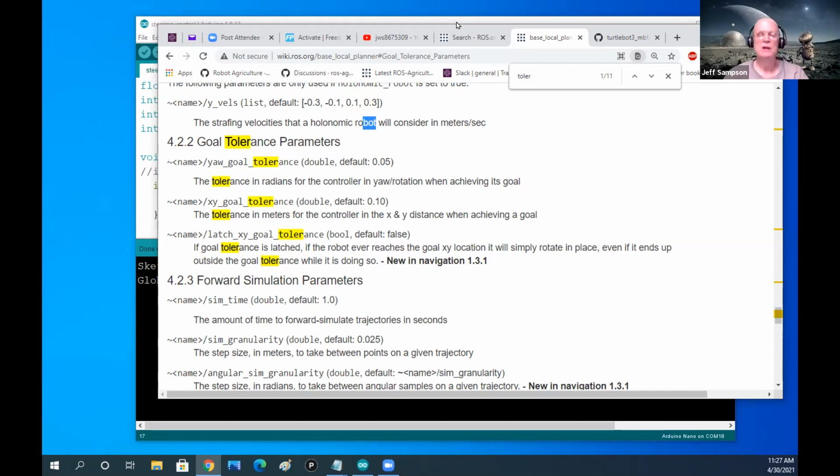So anyway, that's that. I posted the link to that file to give you an idea. Another thing you can do is when you first start up your software, at the very top, it lists a bunch of parameters that it's going to use, and see if it's got the goal tolerance stuff listed in that. Now, it could be that it only defines it if it's not set to a default. If you run your software on your lawn tractor and it lists all the parameters it's going to use, and it doesn't list goal tolerance, but if you run the simulator and it does show goal tolerance, that's something other than default, and that will say that yes, that is modified in the simulator.